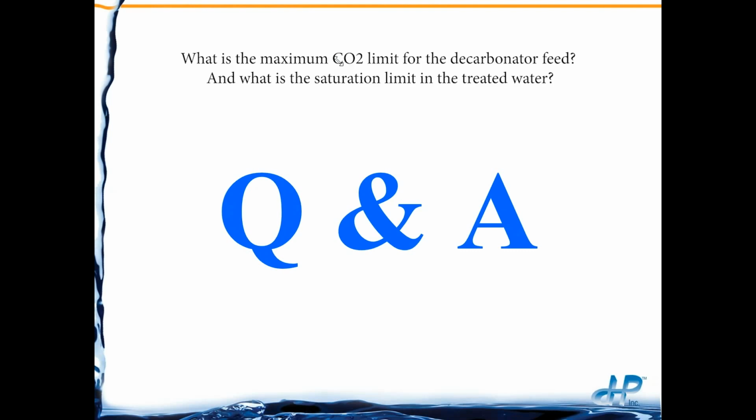Next question: what's the maximum CO2 limit for decarbonator feed? So what is the saturation limit in treated water? Again, it's not a simple question because it's really temperature related. Colder water holds more CO2, warmer water holds less CO2. So as far as saturation limits, it's definitely temperature driven and can also be pH driven.